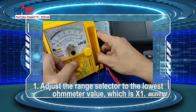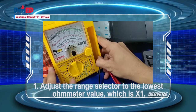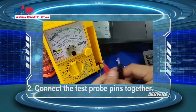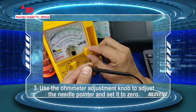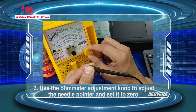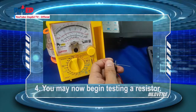Step 1. Adjust the range selector to the lowest ohmmeter value, which is ×1. Step 2. Connect the test probe pins together. Step 3. Use the ohmmeter adjustment knob to adjust the needle pointer and set it to 0. Step 4. You may now begin testing a resistor.